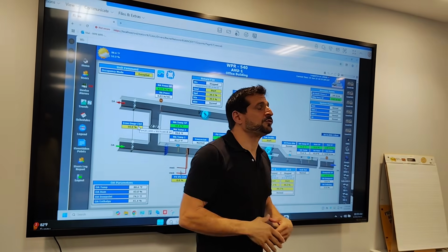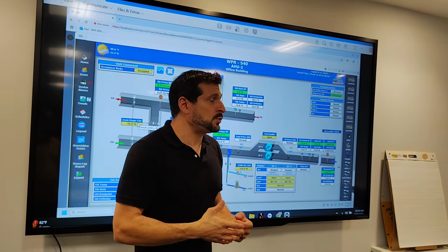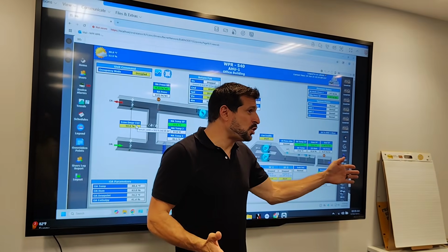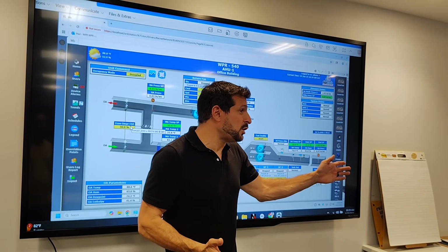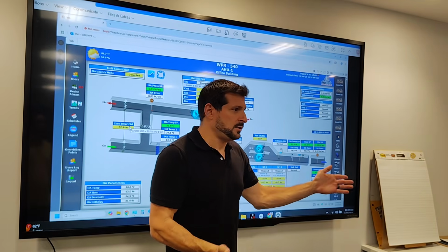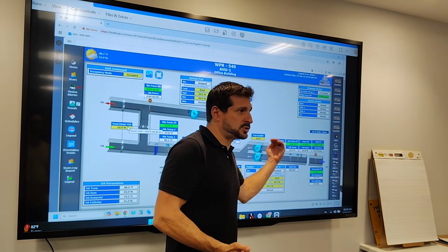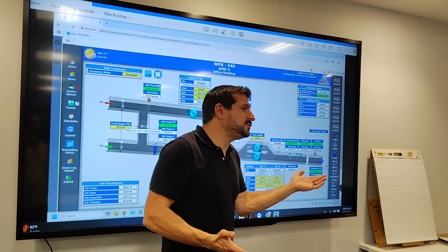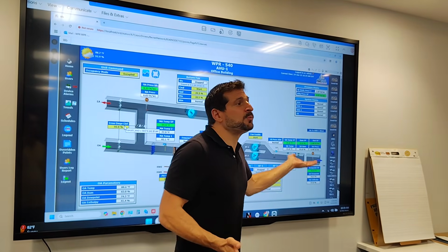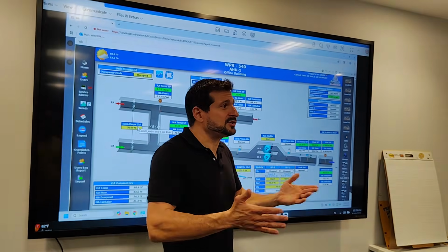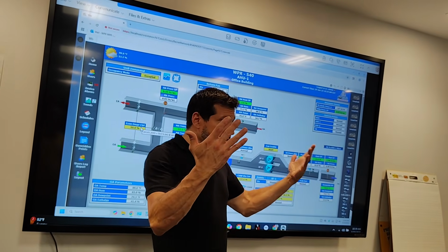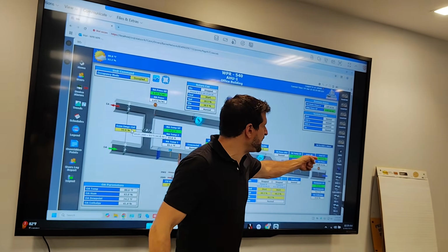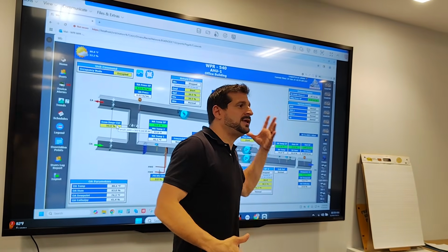And what you do is you look for your most open damper. You say, which VAV damper in the building is the most open? And if the most open one is 95% closed, almost completely closed, well, then we've got too much pressure. Start dropping it. If the most open one is like 60%, all right, we might need a little more pressure than that, because we want to keep these things in a range where they are holding back a little bit and maintaining their set point. Now you have volume everywhere, and you've figured out the lowest number you can keep this at intelligently.